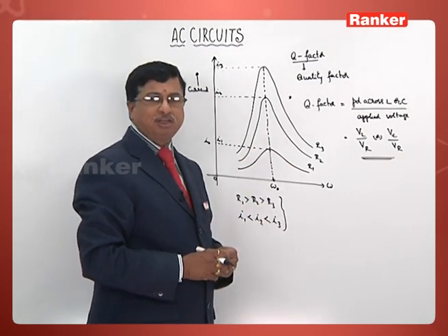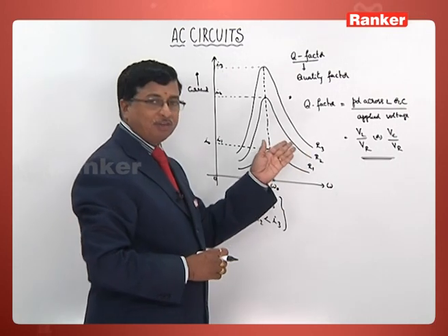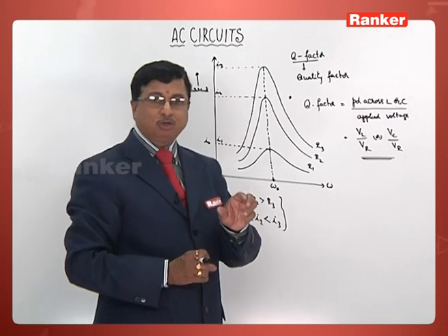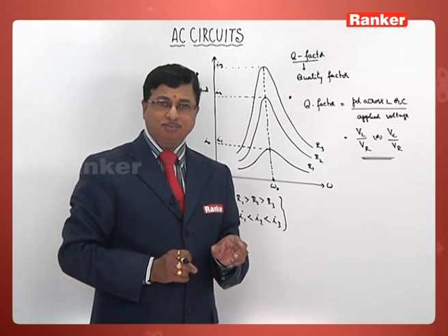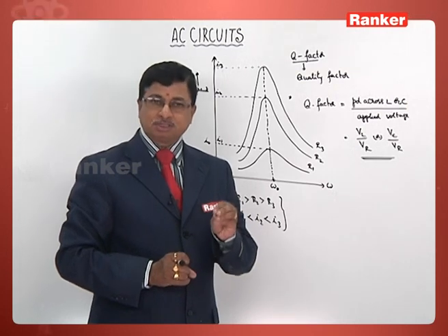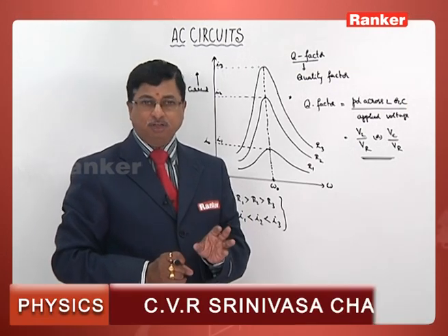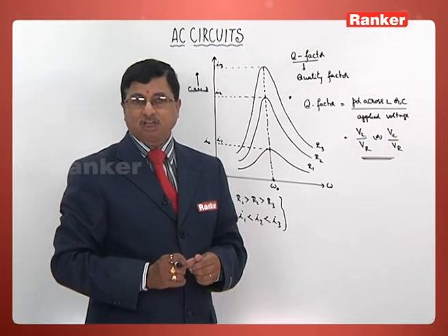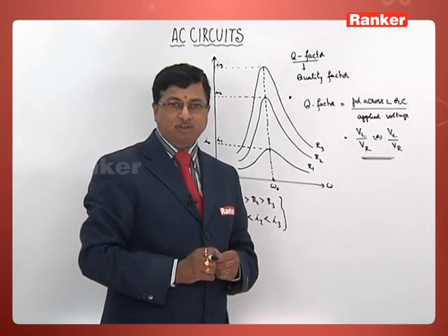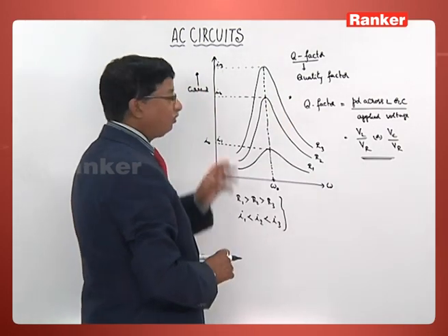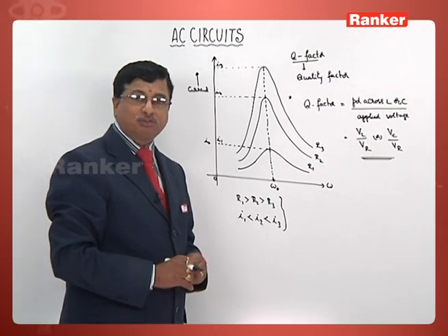Applied voltage is nothing other than the potential difference across the resistance, because whenever the circuit comes into resonance, the effective resistance in the circuit becomes simply VR itself, because the circuit becomes a resistive circuit at that time. That is a point one has to understand. So this is one area we have to remember as far as alternating current circuits are concerned.